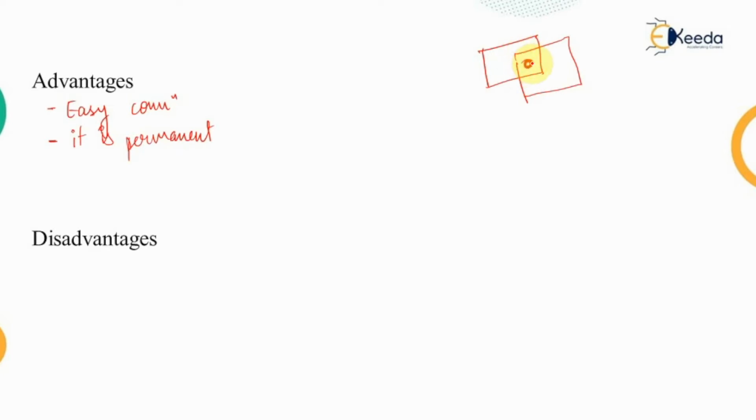Once it is driven in, after cooling down, the rivet will be fixed here. That means this connection cannot be removed. It can only be torn apart. That means you need to replace these two plates, which is the disadvantage of the rivet connection. The connection is permanent, but replacing the plates is a disadvantage.